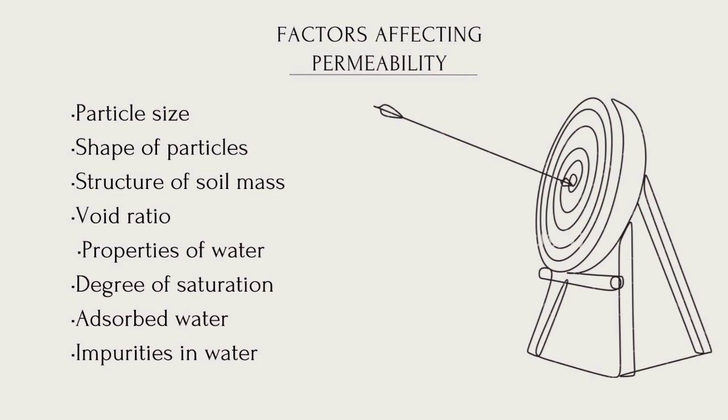Now we will not go into the mathematical equation but only the theoretical. So talking about the soil structure, the structure of any two similar soil masses at the same void ratio need not be the same. It varies with the level of compaction applied. If the soil contains a flocculated structure, the particles are in random orientation and permeability will be more in this case.